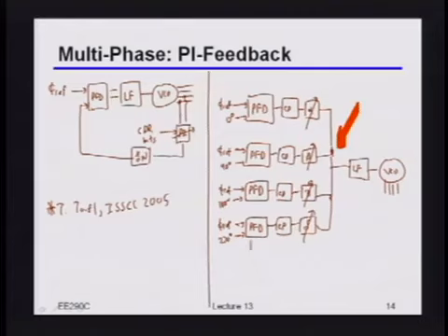So all of the weird transient junk and errors that I might be picking up here gets smoothed out by working on that low bandwidth node. As you'll see, maybe not today, maybe next time, this turns out to be a lot easier to build than a really good phase interpolator would be. Because here I'm really just working on average quantities. Whereas when I'm dealing with a phase interpolator, you have to balance things just so nicely so that it really works the way you want it to.